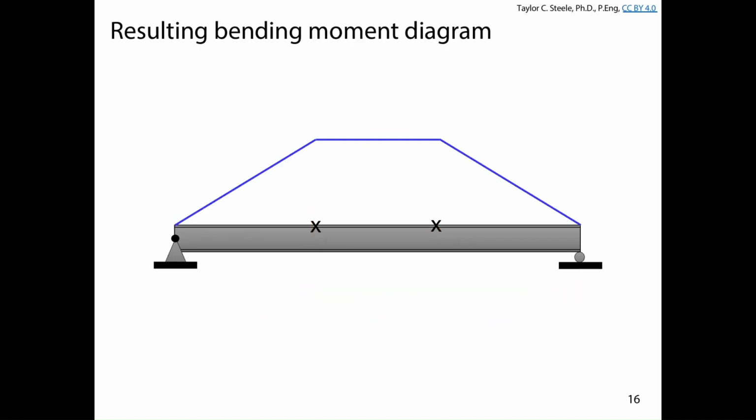Right, so if we look at the shape of the moment diagram, the moment is equal on both sides, so the entire top flange is in compression. The other ones have moment of 0 and 0 at the start and end respectively. And so, if we look at the segment overall, this segment has the same factored moment on it, right? There's going to be a moment at the right-hand side equal to whatever M is here. So maybe I'll just write this as M,